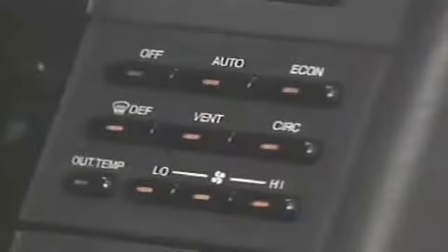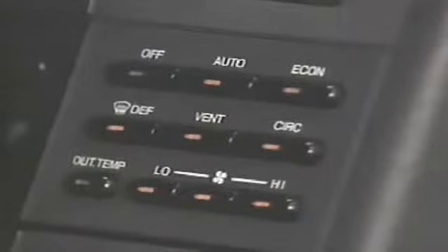The system automatically enters the bulb and actuator check mode. Each LED, except off and outside temperature, will illuminate as amber, then change to green. The temperature indicator displays full lighted segments, and each actuator moves through approximately one full cycle of travel.